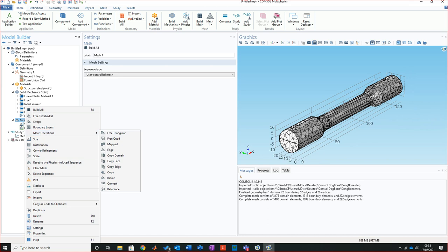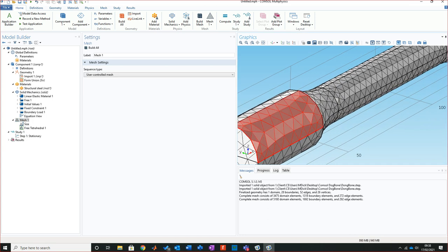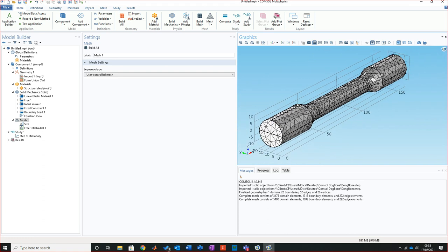You should be starting to realize that something like a tetrahedron in this case is not really going to do its job. Tetrahedrons work in some cases around here, but I think we need to combine quadrilaterals with tetrahedrons to give a better representation of what we're attempting to do.